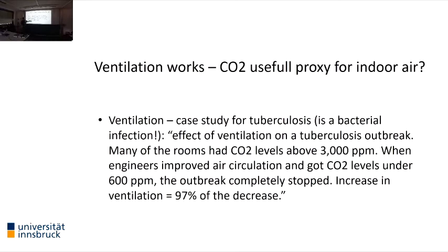They saw that increase in ventilation, 90-70% of decrease in the transmission rate, and they found that 600 ppm is kind of a rough threshold for that disease, where you keep the ambient concentration of CO2 that accumulates because we exhale CO2. CO2 is just a proxy here, of course, it has nothing to do with the virus, but it's a proxy you could use to say, well, if you stay below it, you're kind of in a green zone. So that's, I think, one message from that.